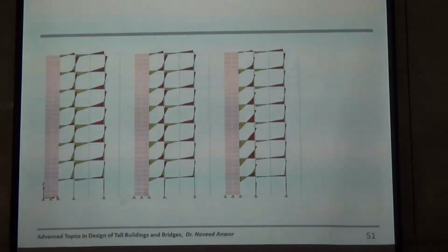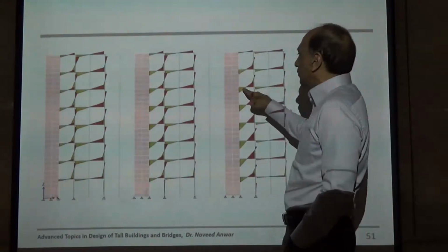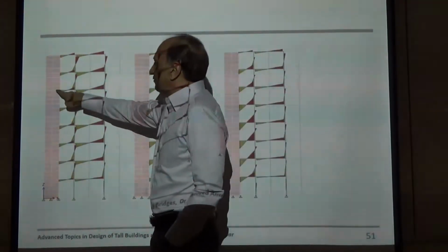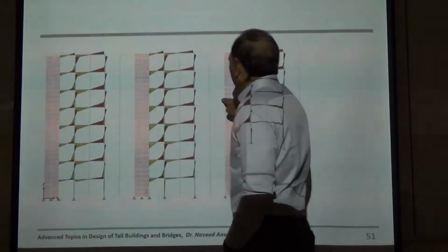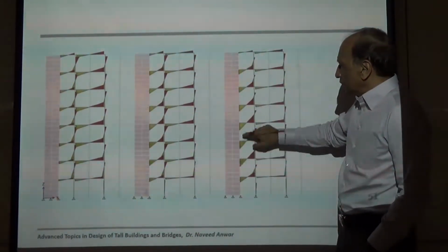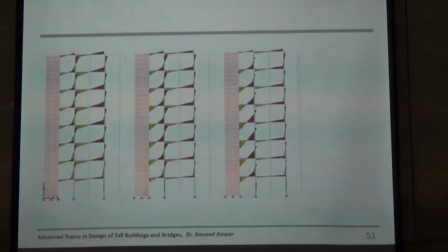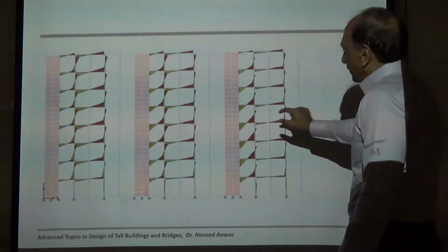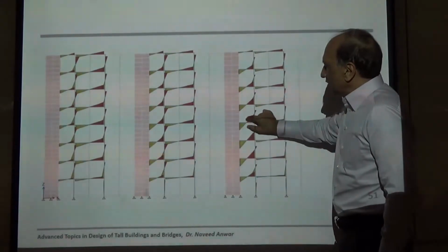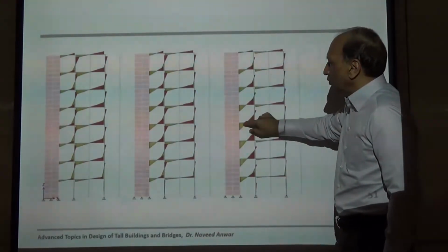The bending moment between these, not shear force, this is bending moment. This is the bending moment for this beam here, and here the bending moment is quite large. So there is a large bending moment in that link beam, which is helping to couple the frame with the wall. And if this beam does not have enough capacity for the bending moment, you may want to increase it.